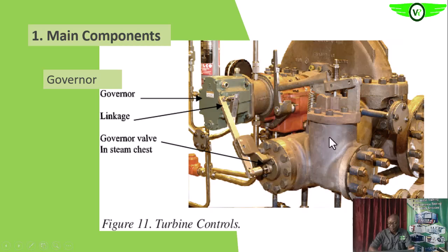When you look at this stop valve, you see that it has a lever that you can hang on, that is the trip mechanism. So before starting the turbine, as we'll see later during normal startup, you lift this up. So as you are lifting this up, what happens?